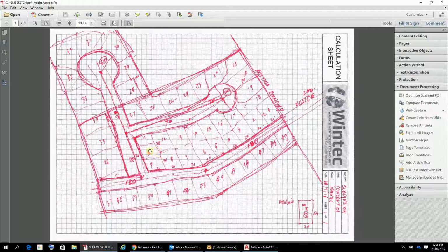So I've got to have some consideration as to what I'm going to do with these corner sites and how that will fit in with my module. So you can see that the depth of these determines this here. We probably want a depth in here of around about 30 metres, or possibly a little longer. So that's got to come into the consideration of the cul-de-sac head. I'm going with a 10 metre cul-de-sac head. That'll be a 10 metre carriageway situation. So I'll look at how the boundaries for that fit together.